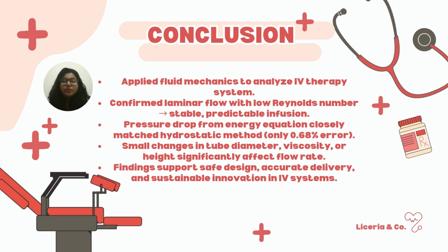In conclusion, this report showed how fluid mechanics helps ensure accurate and safe IV therapy. We confirmed that the flow is laminar and predictable, and our calculated pressure drop closely matched the hydrostatic estimate. These findings highlight how small design factors can significantly impact flow, reinforcing the importance of precision and sustainability in biomedical engineering.